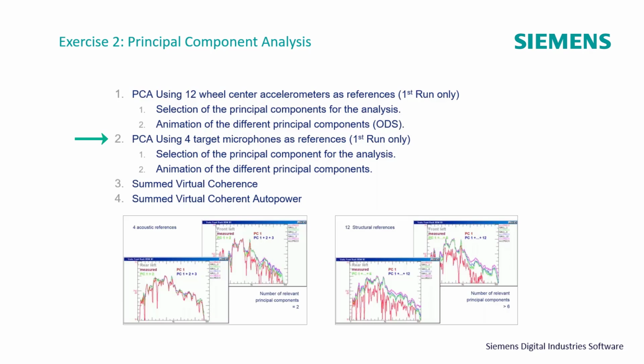Then we did a second study where we used the 4 microphones as the references. Again, we used the same first run, and then we did the principal component analysis. And again, we can animate those to look at the different acoustic phenomena acting on the structure instead of the structural phenomena.